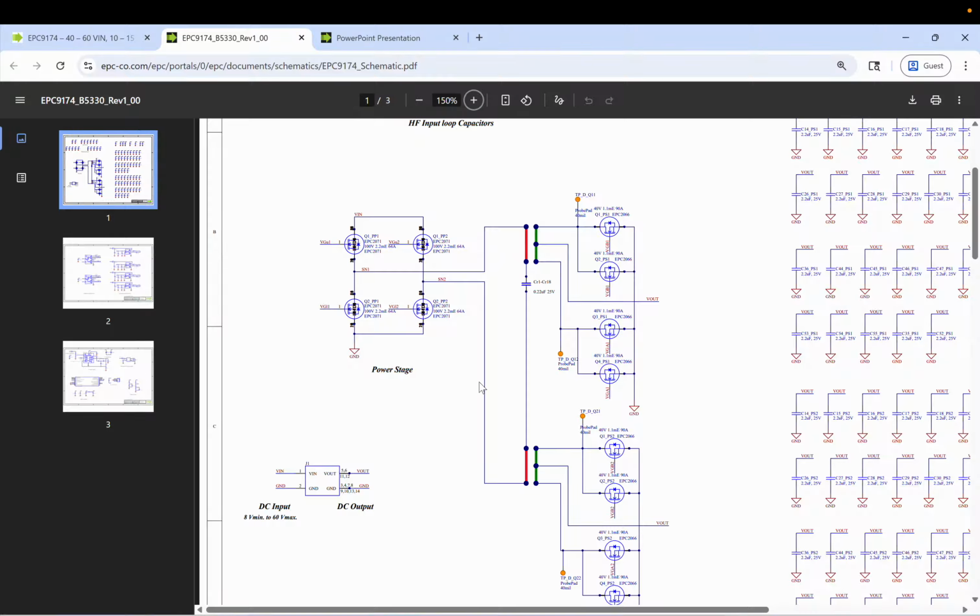When current flows like this, the positive turn is this specific loop where these MOSFETs turn on and these MOSFETs turn on. So this is the positive, and during the negative these two MOSFETs turn on and this loop is on. This is the negative loop.